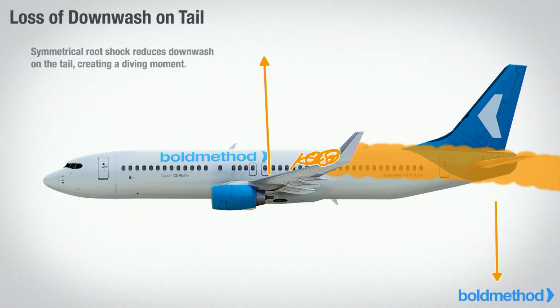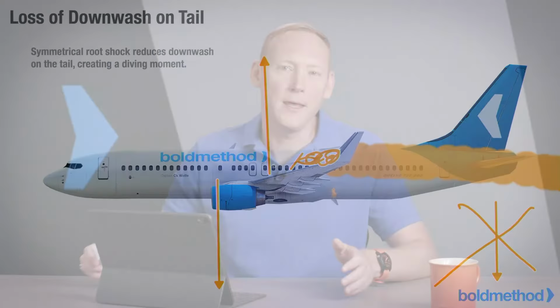And even if the center of pressure has not changed location, you've lost essentially that right there, and so the aircraft starts to pitch nose down. So even if the center of pressure doesn't move around on the wing because of a wing root stall first, if the separation behind the shock wave starts to blanket the horizontal stabilizer, now you lose the ability to generate tail down force, and the airplane wants to tuck under as well.